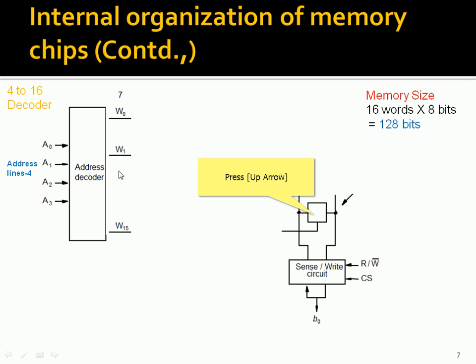Also, the write control signal, which is an active low signal, will be sent from the processor. Bit b0 will be the LSB of the data, either input or output. From this simple diagram we should be able to appreciate a single memory cell built with a flip-flop.